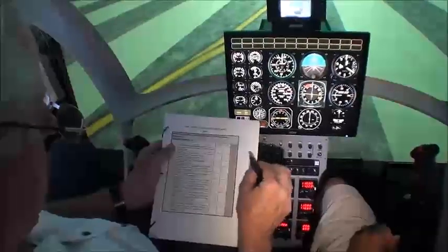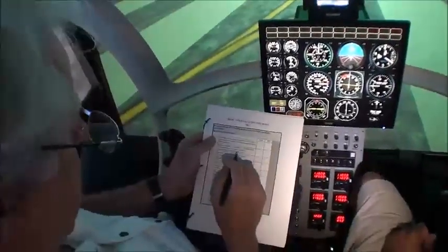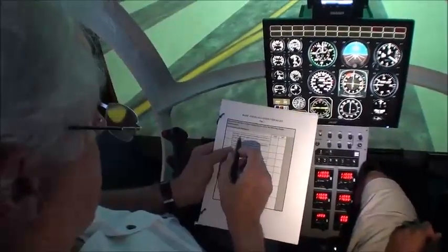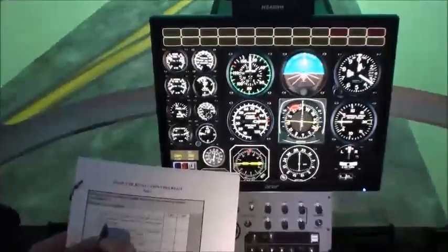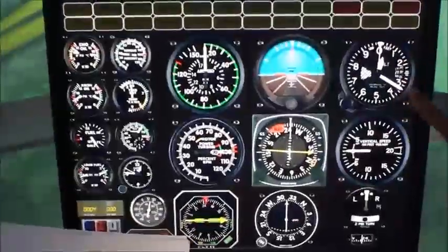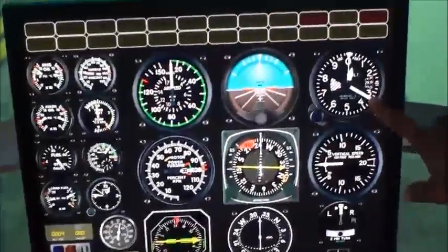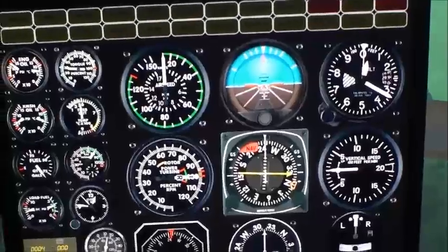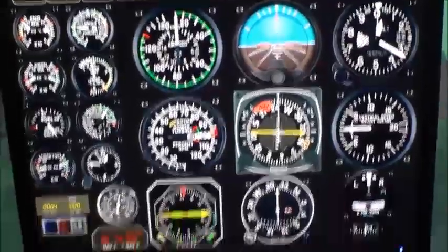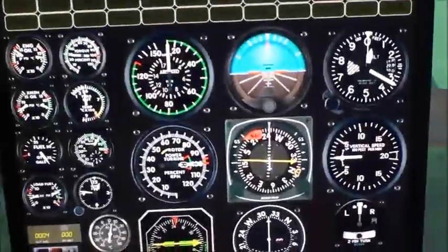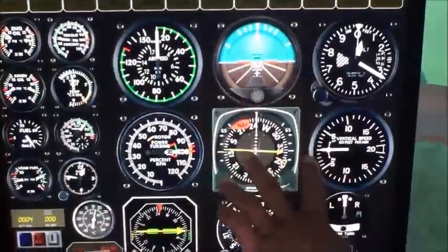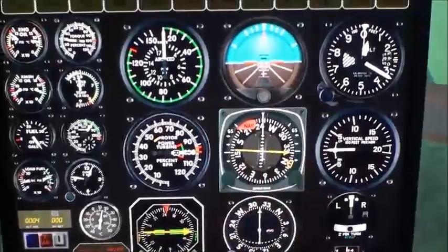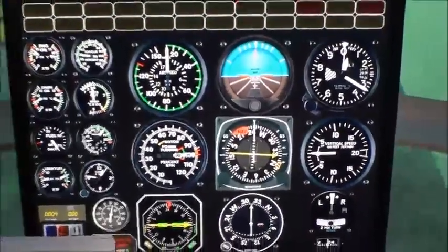All of these items are duplicates, but we're going to go through them since they're on the checklist. Number 1 is altimeter with incremental markings each 20 feet or less, operable throughout the normal operating range of the helicopter. Here's the altimeter, and it also has a baro adjusting knob. Yes. Flight instruments in a standard T configuration. So here's our six-pack.